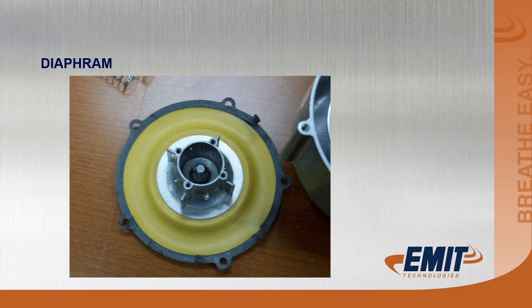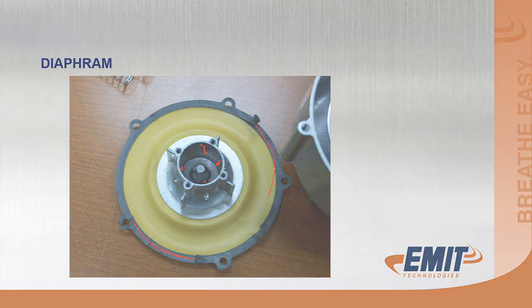This is a typical diaphragm out of an IMCO carburetor. If this was worn out, you'd see notches worn down in here in 4 different spots. And if you see those, just replace it. Typically the carburetor's worn out as well. The other thing is this gasket is in really bad shape around this one. If that doesn't seal, the diaphragm doesn't react correctly.